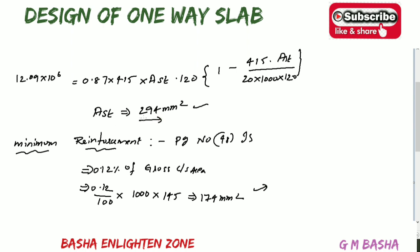So we are using this one. The minimum is only 174, which means we are using more than that. Therefore area of the steel will be greater than area of the steel minimum. So it will be okay according to our condition. For example, after solving the equation based on the bending moment, you may get some 150 mm square, but after solving according to the cross sectional area you will get 174.